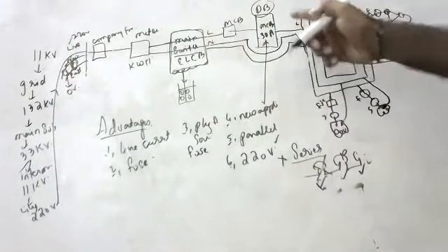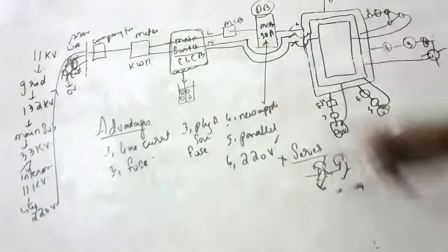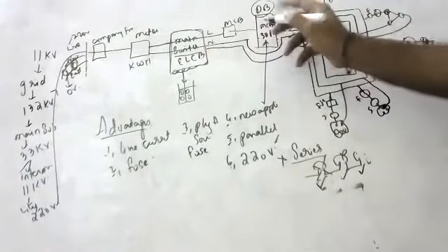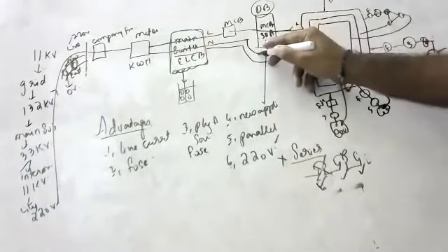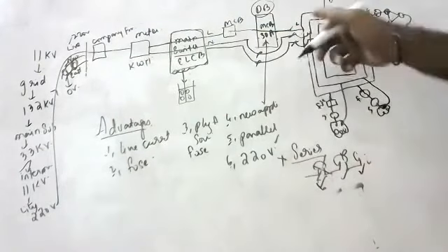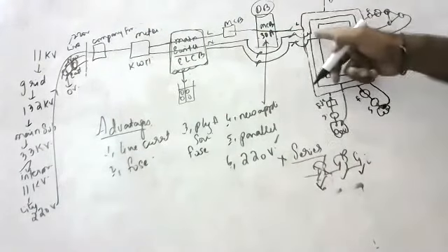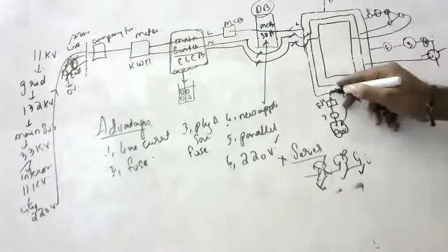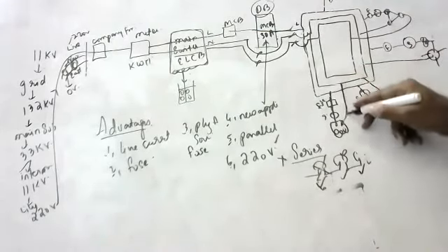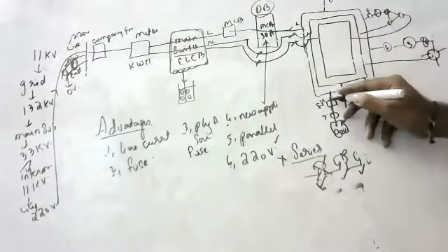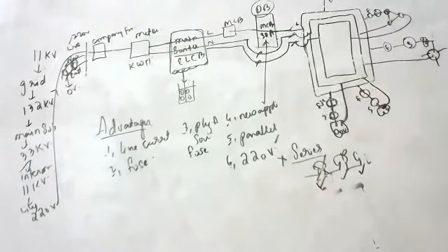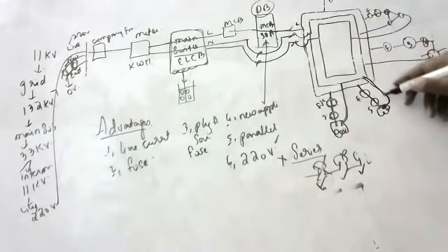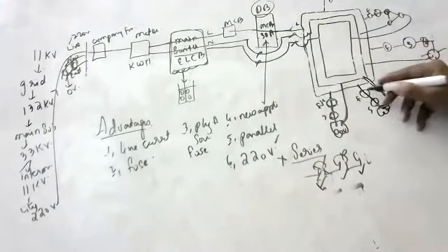From the distribution box, three wires are coming. Every distribution box will have an MCB. The live wire only will go through the MCB; the neutral wire and earth wire won't. Ring system: full live wire, neutral wire, earth wire. Wherever you want, take one connection from the live wire and one connection from the neutral wire. But the live wire should have its own fuse and its own switch.